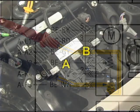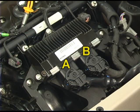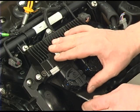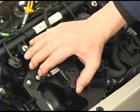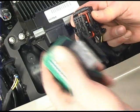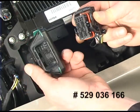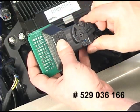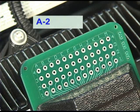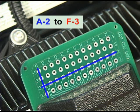To perform the electrical test at the ECM, first remove the proper connector from the ECM, in this case, connector A. Insert the ECM adapter tool into the correct connector. As an example, let's say the shop manual specifies a test between pins A2 and F3. Locate the A2 test point. Locate the F3 test point.